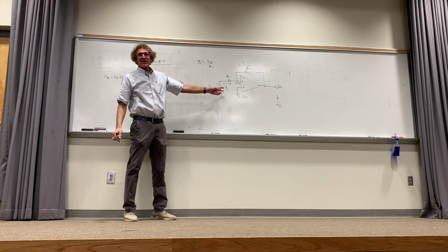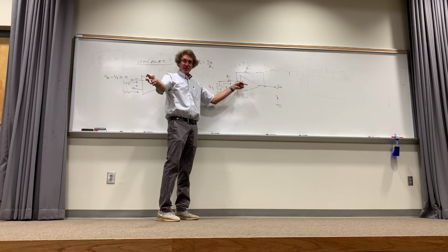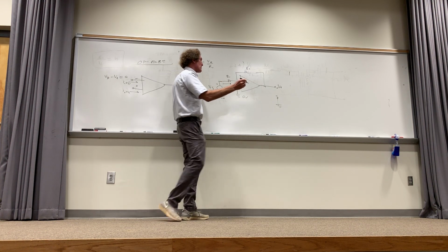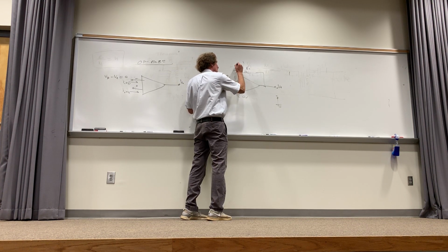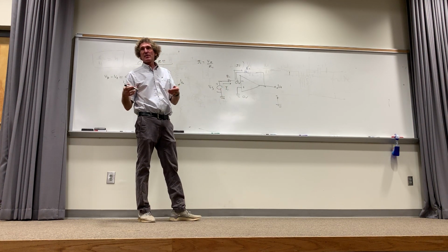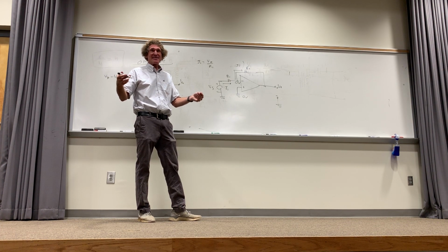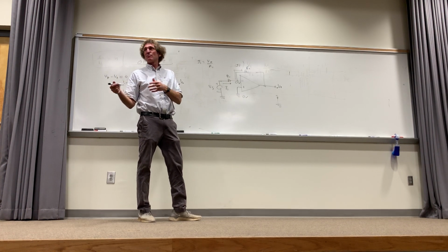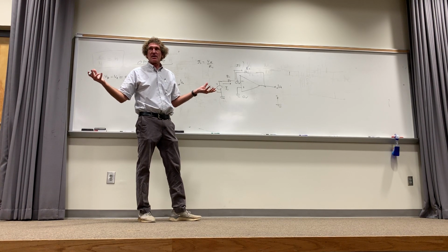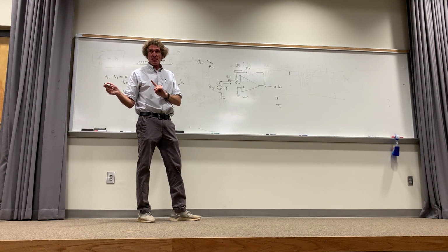All right. So if that's I1, how much of that current goes into this terminal? I told you it was 0, right? None. Where does it have to go? It goes this way. Are you seeing this? I'm doing it this simply because if you see the simplicity, you won't mess up. It's when you start memorizing all these formulas that are out there that you'll blow these things every time. There are cajillions of formulas for operational amplifiers, depending on the configuration. You do the analysis this way, you never mess up. Do you all see what I'm doing?